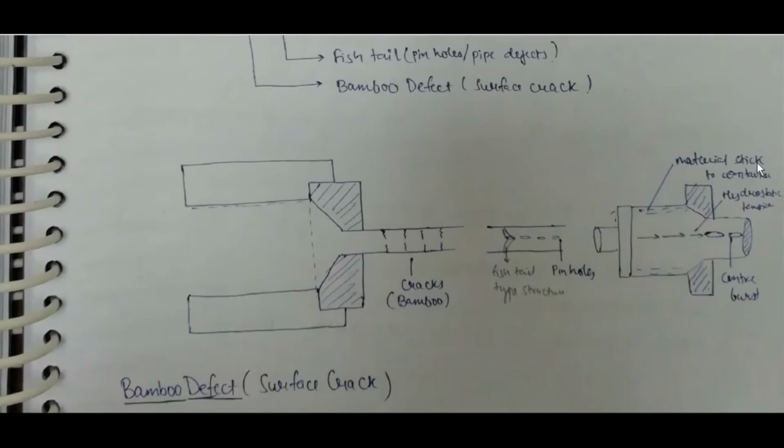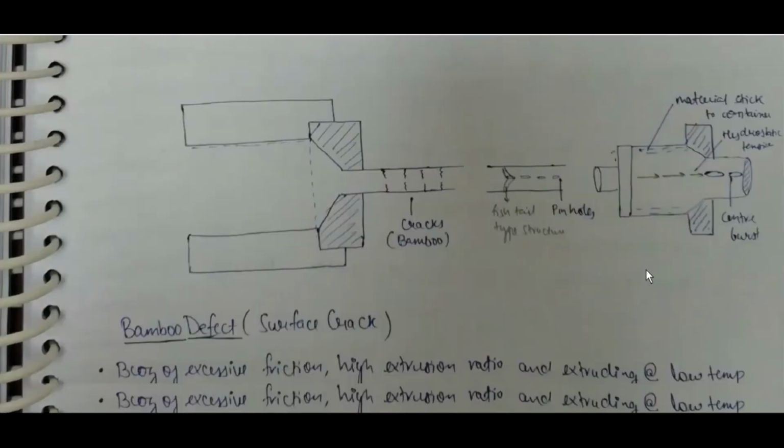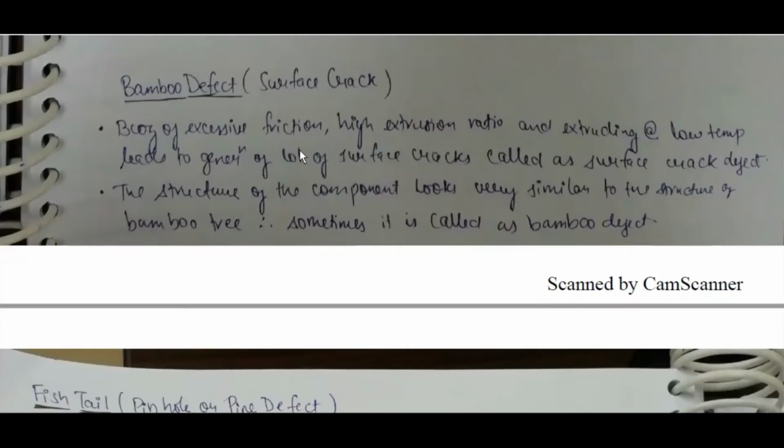Classification of forging operation based on type of force applied, based on source of force taken. Hand forging: whatever the force required for deformation, if it is taken from human hand, it is called hand or man forging. Machine forging: whatever the force required for deformation is taken from a machine, it is called machine forging.